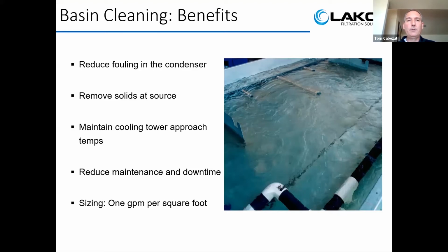Basin cleaning benefits, which we kind of went through some of those already, but you can see an actual installation. It's fairly straightforward. It's PVC piping, extensions, and then our hydro booster nozzles. For those of you that are aware of those, we have the blue ones that go with our older, I'll call it, style TC packages, and then the yellow ones, which are the newer ETCX series packages. So you want to make sure also that we're applying the right hydro booster nozzle to the filtration skid that you guys have selected.